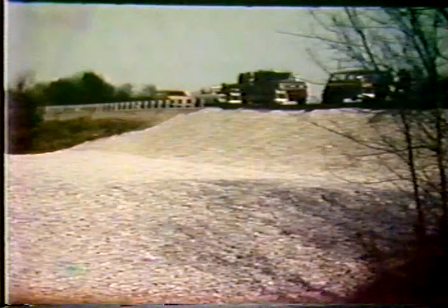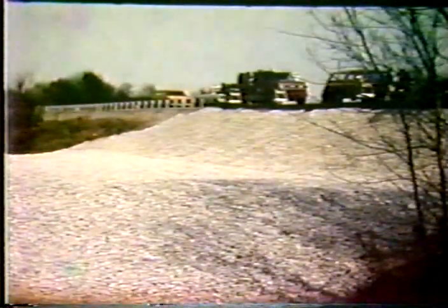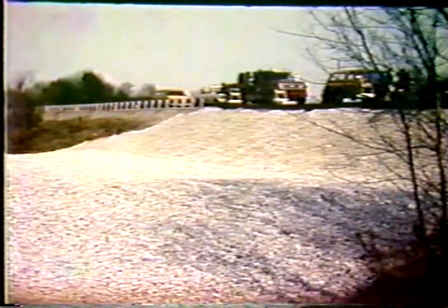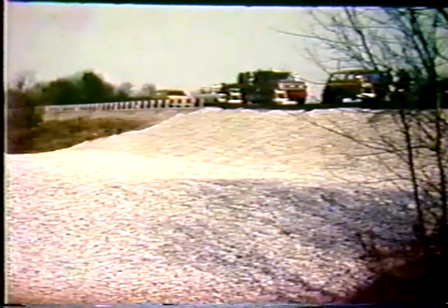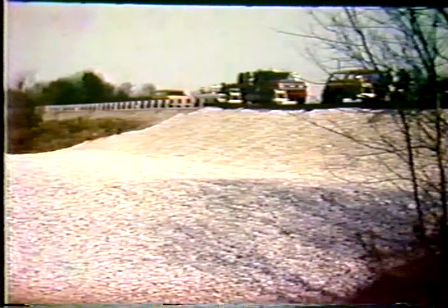Another view of the slide and the finished product. What we ended up here with is 3 things. Flattened slope, which is shown at the top, which is about a 3-to-1 slope. We've got a berm now in place, and below that berm, we've got a shear trench. And I think they got by without having to buy additional right-of-way. It was a very nice repair job.